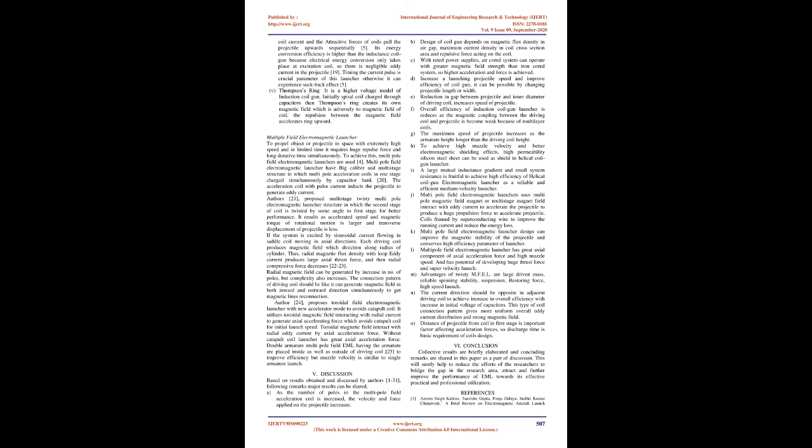Reluctance of a magnetic circuit is equivalent to the resistance of an electric circuit. As there is a magnetic field produced by the coils, the reluctance of the coils is required to calculate l1. The basic formula for reluctance is given. The force generated on the projectile is calculated from the electromechanical energy conversion principle, which uses the magnetic field as a coupling medium between the electrical and mechanical systems.